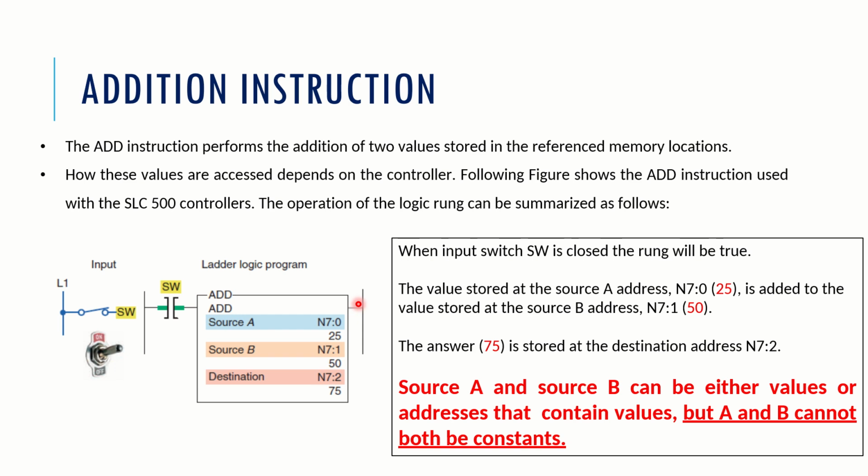Under those circumstances, the BCD has to be converted to decimal and then placed here. Whenever some analog input is taken at an input bit, the input signal coming inside the PLC is stored in this N7:0, from which you can get this particular value.